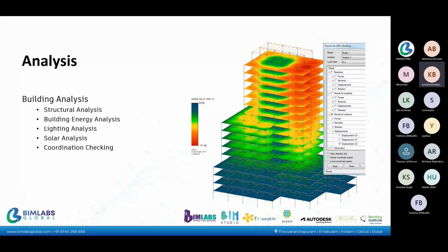Okay, and now in Navisworks, we can do clash detection, as well as quantification, and we can do animation scripting. In Revit we can do renderings and walkthroughs. We can walk through our model in and out, and experience how the building will be. Like that, in Navisworks also we can do the animation. We can walk through a residence or a building. If you come near a door and want to open it, using the Animation Scripter function we can do that: when you touch the handle while walking through, the door opens. You can record a video and send it to the client, and it will be helpful. So Navisworks is the software for all these things.